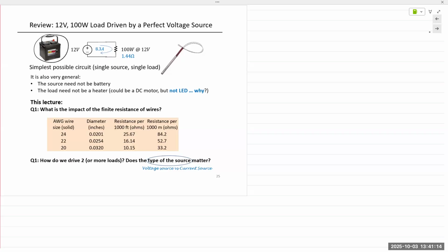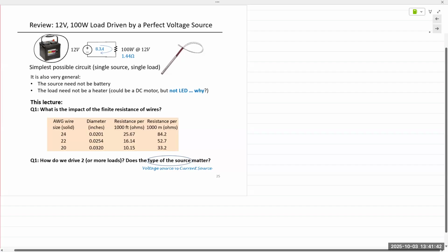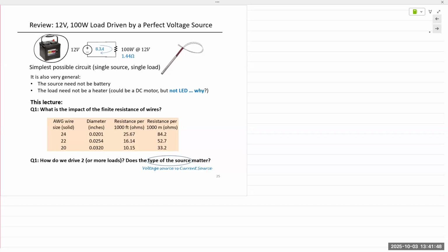Theoretically, when we are performing analysis on paper, that analysis ignores any resistance of the wires. In real life, we must consider the resistance of the wires, but only in certain cases. Again, this USB cable is 3 feet or less, and so whatever resistance it has, it's not going to affect anything. Now, if I increase the length of this USB cable to 100 feet or 200 feet, that resistance could perhaps affect the transfer of data. So it depends. Those are the kinds of considerations we need to take into account.